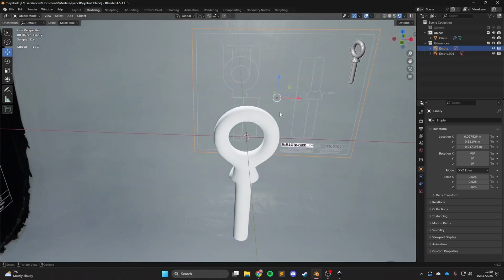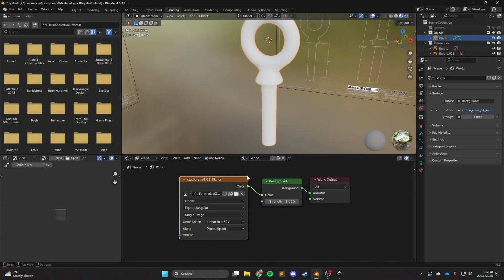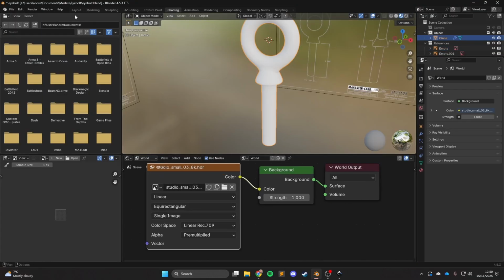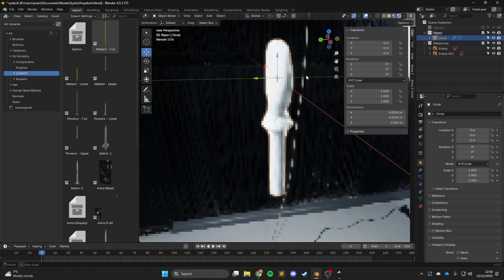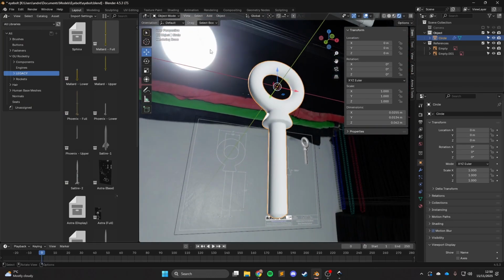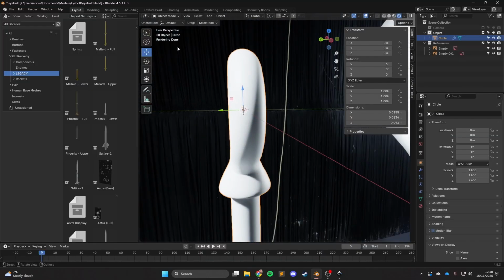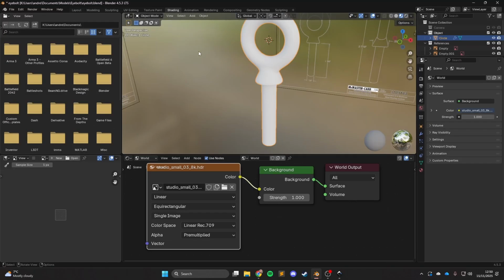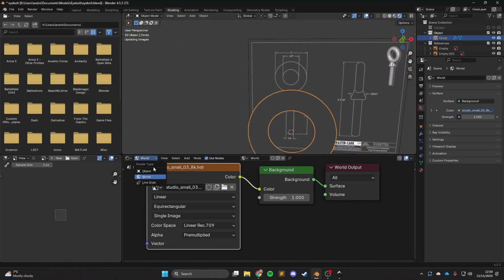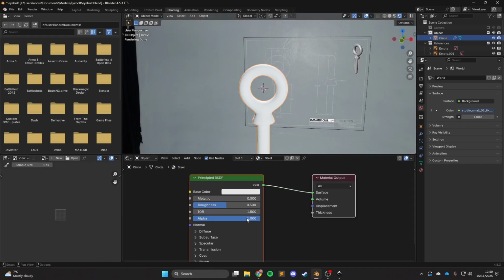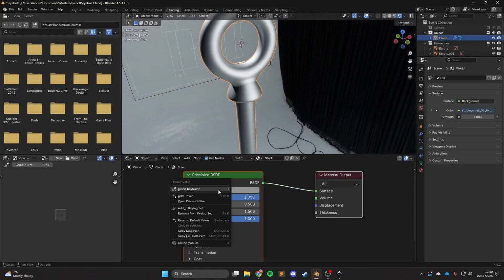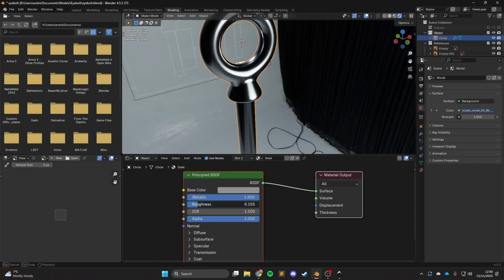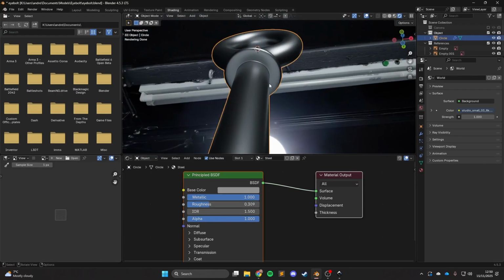So now if you go into render view and you give it a second to load the image, you've got this sort of studio view around you, and it just gives you some really nice lighting. And make sure it's a HDR file, because if it's just an image file, you won't get these really bright lights. It'll kind of cap off. They'll actually give you lighting in your scene. So now if we go back to shader type object, we can just make a quick material, metallic 1, color down to like here, roughness, let's just do about there, something like that.